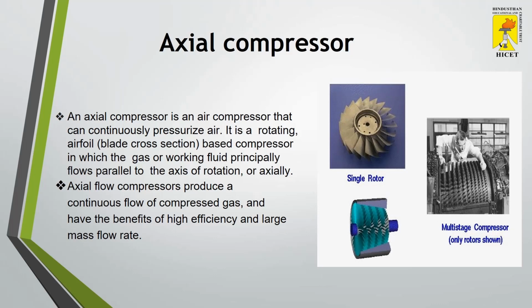To get the required pressure, any number of stages can be stacked together and a multi-stage compressor can be made to reach the required pressure. Axial flow compressors produce a continuous flow of compressed gas and have the benefits of high efficiency and large mass flow rate.